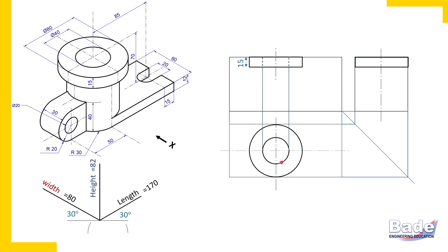Now I am projecting the hole, the corresponding dotted lines. So where is this hole in the front view? Here it is. It is a rectangle and it is a dotted rectangle. Now transfer this hole to the side view also. In the side view also it is a dotted rectangle. So here is that hole in the side view. So have you realized, in the top view a circle, in the remaining two views a rectangle? Using this simple logic we have drawn 3 views of this disc.